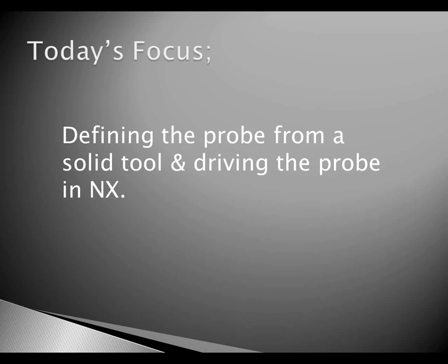Today's focus is going to be on how to define a probe from a solid tool and how to drive the probe in NX. A post-processor with the appropriate code that outputs the Renishaw macros will be required to get the proper NC output. While NX can output either a Siemens or a Fanuc controller, we'll just be working with the Fanuc. And so let's see how this might work.